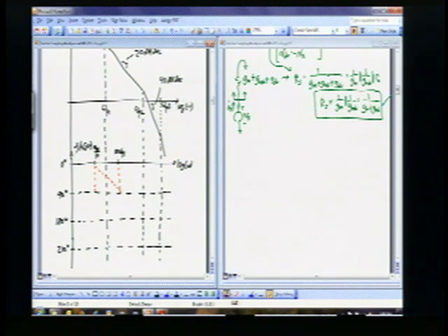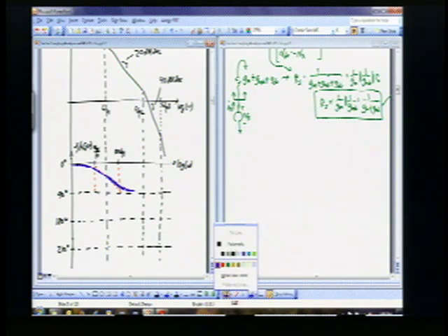So my phase curve now looks like this. Comes out like that. It goes through that asymptote like that, and then curves out like this. Okay, so that helps me to draw the phase for that particular pole. That's how the phase changes as the frequency goes through that particular pole. Okay, and I can do the same thing with the rest of these poles. And so, for example, for this pole, I can go 10 times down, 10 times up.